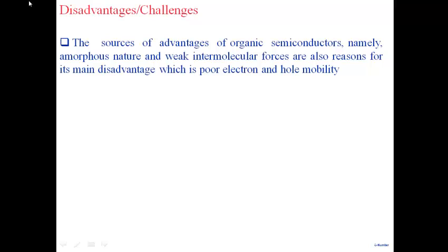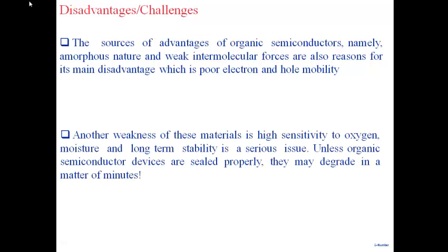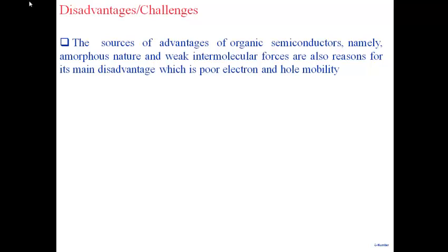The place where you really need mobility is in a transistor. If I have a low mobility, my transistor switching speed will be low. So that's the place where it is extremely important. But then I have many applications. Suppose I'm making a temperature sensor. It has to sense the temperature, and then the value that you get, you want to convert it into analog, or into digital and all of that. Now, how much speed do you need for a temperature sensor?